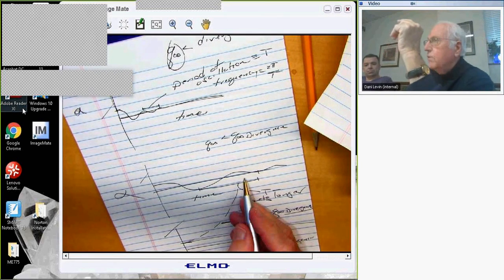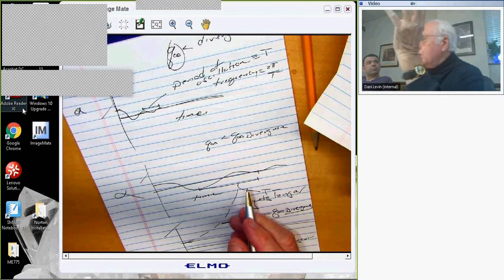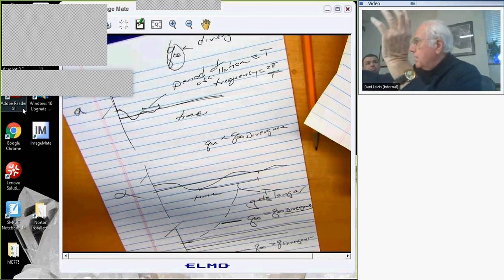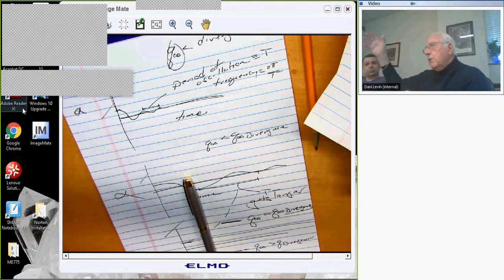If you have a nonlinearity in the structure, which you might have, then this would not go on forever. It would at some point reach a finite value and stop, because the nonlinear spring characteristics would be more than sufficient to offset the negative tendency of the aerodynamic force. So we've left out nonlinearity. So in both flutter and divergence, sometimes you don't go off to infinity as linear theory predicts, but you go to some finite value. Even so, most aerospace companies do not like to fly their airplanes at values of flow velocity beyond the divergent condition or beyond the corresponding flutter condition.